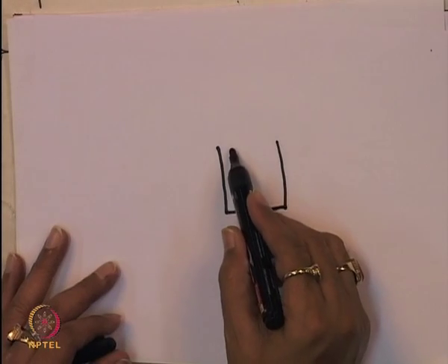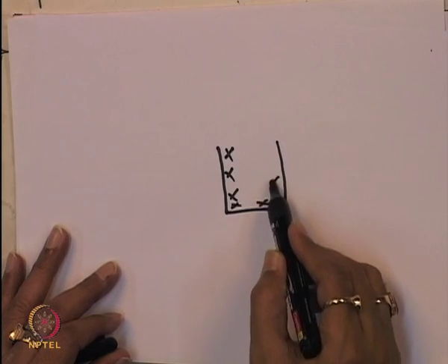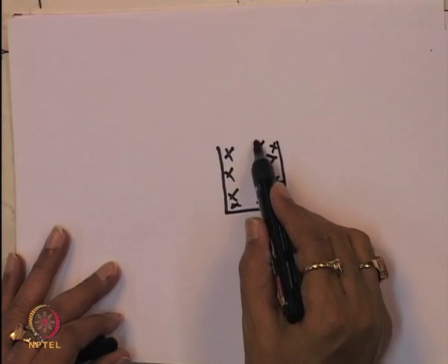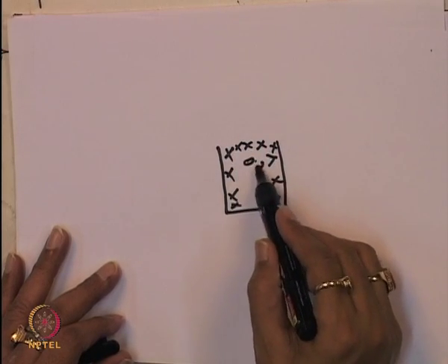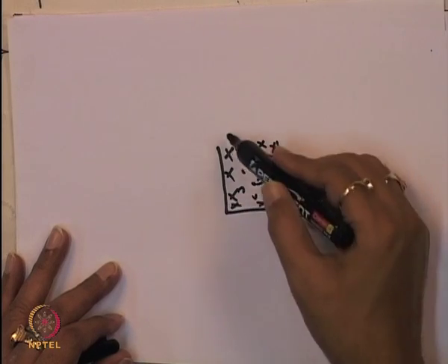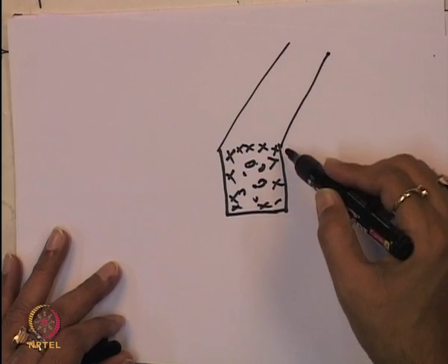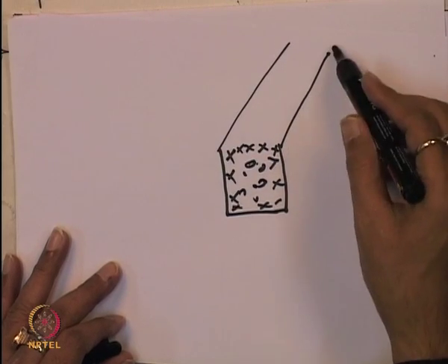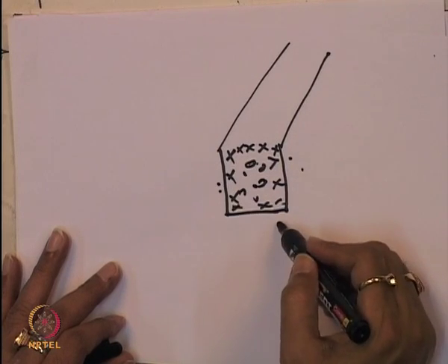So when you place the geotextile material like this, this is the aggregate and this is all along this length. So this length is 50 meter and the size of the drain, let us say, is 0.27 by 0.27.